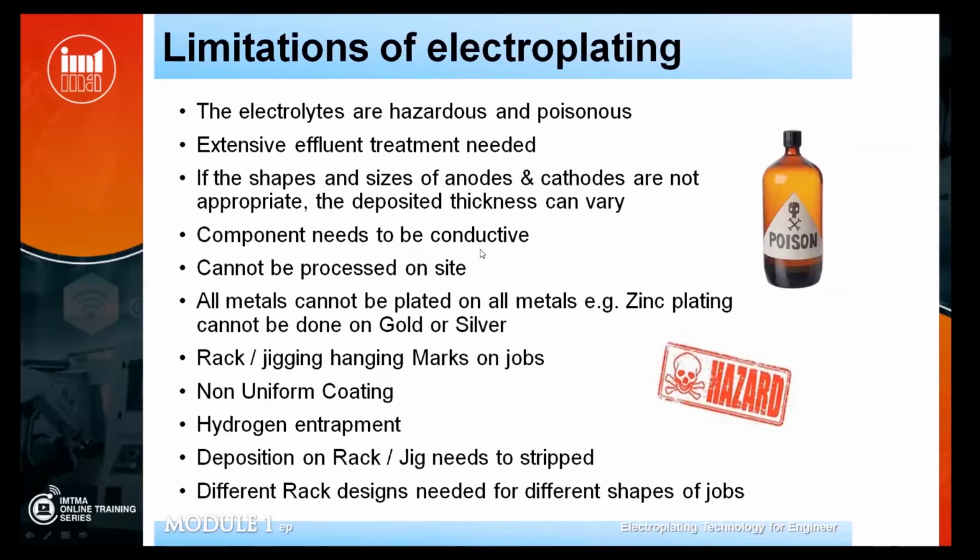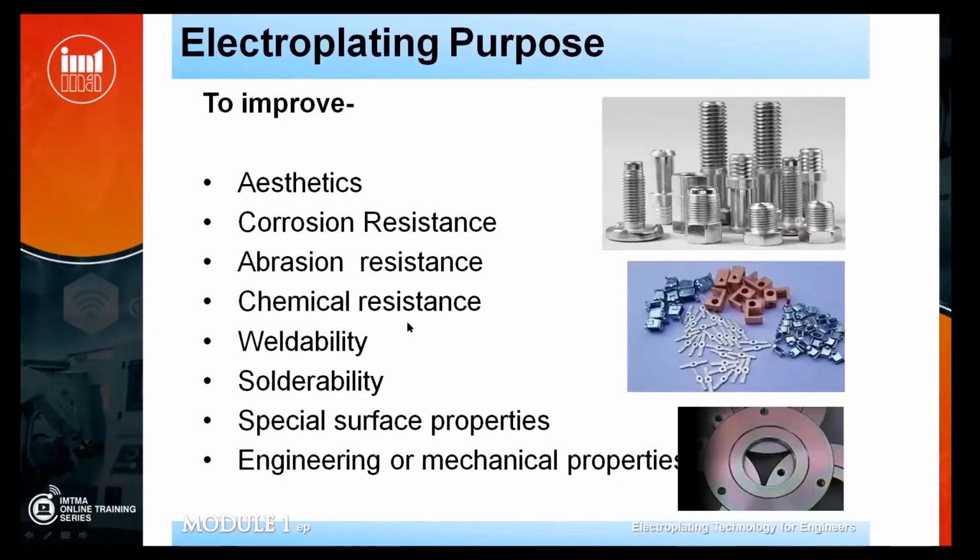Component needs to be conductive, cannot be processed on site. This is one big limitation. Painting you can do on sites, powder coating you cannot do on sites. Likewise, plating also you cannot do at sites.